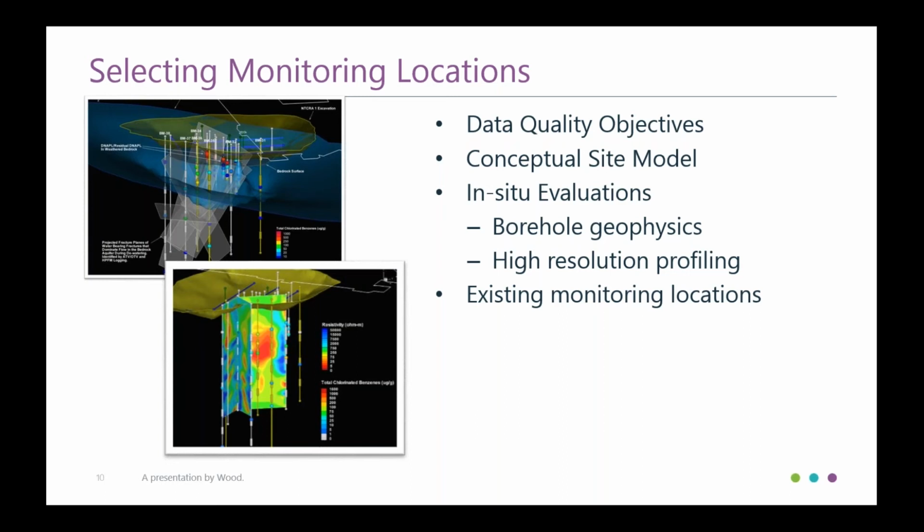And this is, if you're doing bedrock, you probably start looking at some in situ evaluations with borehole geophysics or high resolution profiling to figure out the distribution of contaminants in the aquifer that you're evaluating. And then something to think about, I've got some slides on what to think about if you have existing monitoring wells and how you can use them and how they may be limited.